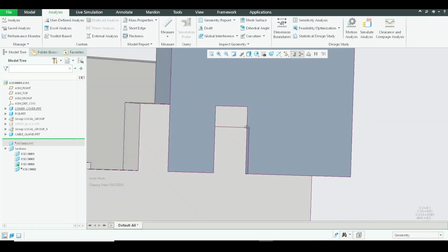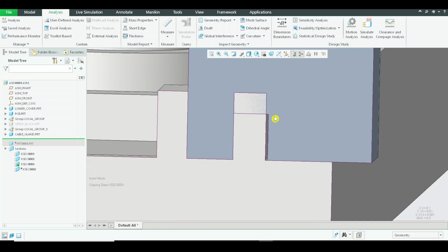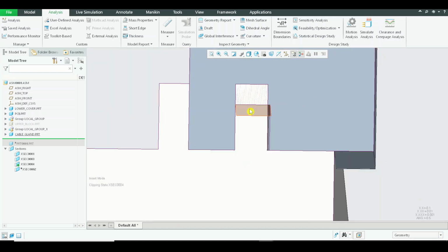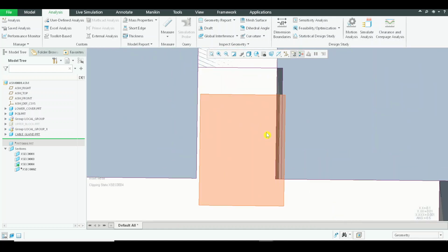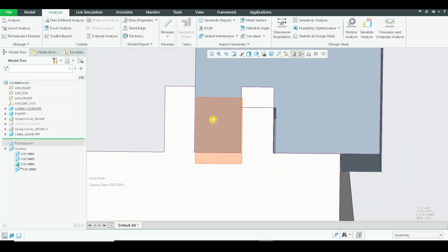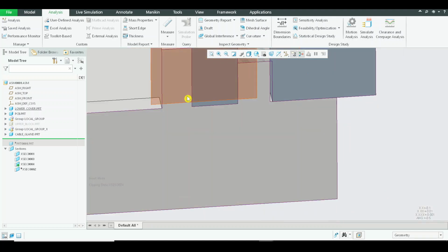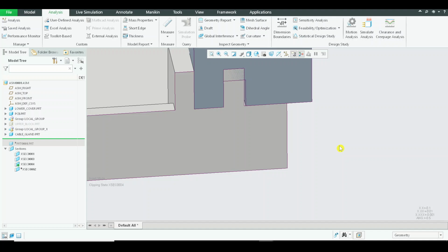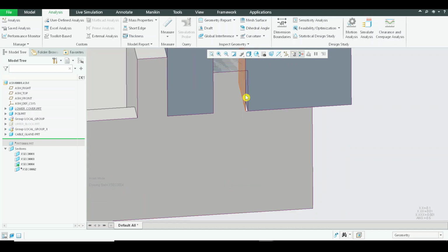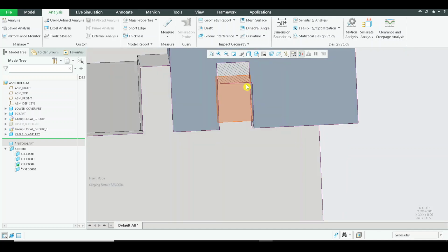But the thickness is a little bit larger. My goal is, this is a rubber material, okay, so it shouldn't have much clearance because it has to be tightly fixed in the slot of the plastic material, okay, so it has to be a very tight fit. So rather than maintaining some clearance, we will be touching the parts together, okay.